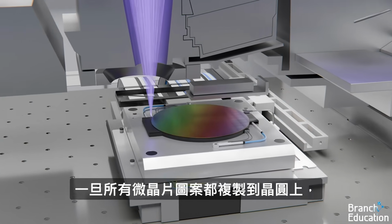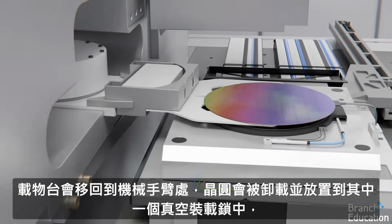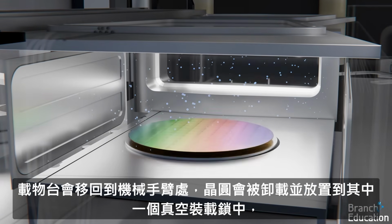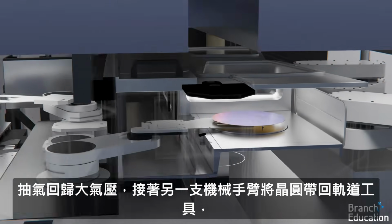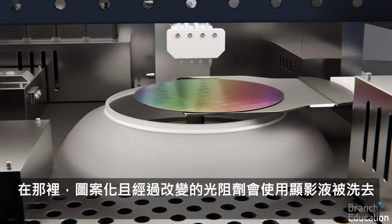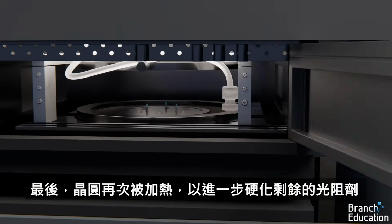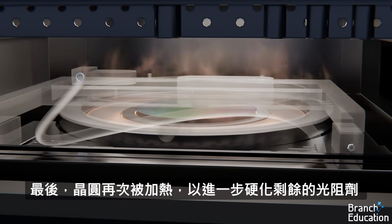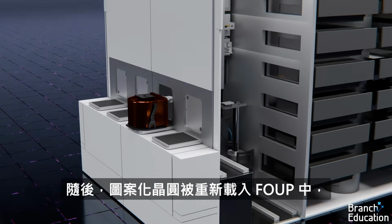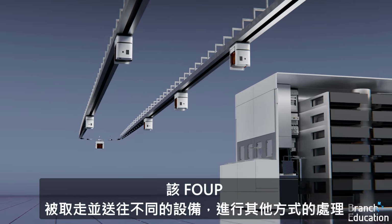Once all the microchip patterns are copied to the wafer, the stage moves back towards the robotic arms where the wafer is unloaded and placed into one of the vacuum load locks, pumped back to atmosphere, and then a separate robotic arm brings the wafer back to the track tool, where the patterned and modified resist is washed away using a developing liquid. Finally, the wafer is heated again to further harden the remaining resist. The patterned wafer is then loaded back into the FOUP, which is picked up and brought to a different tool to undergo processing in other ways.